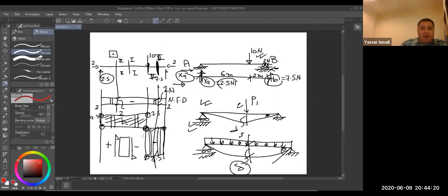From the normal force, I will calculate the normal stresses. From the shear force, I am going to calculate the shear stresses, which I need to study the deformation of the section. And from these values, I am going to calculate the area of steel, the section's dimensions, and all the properties of the section.